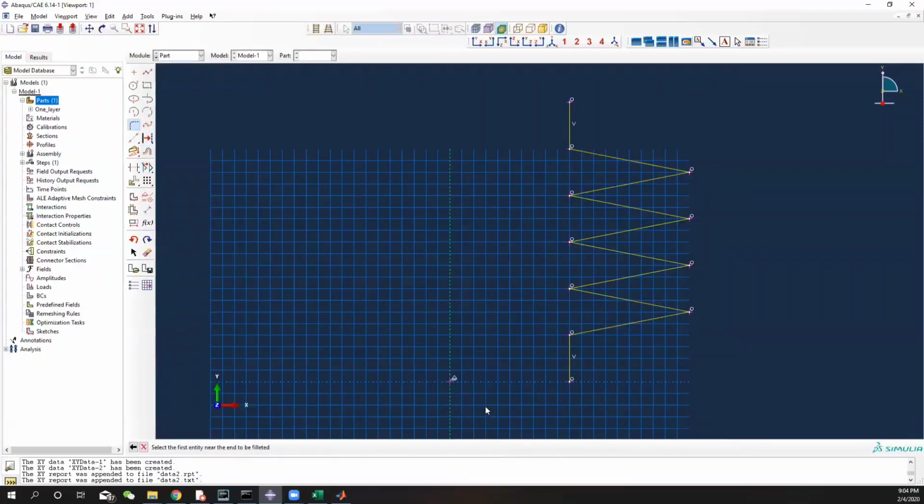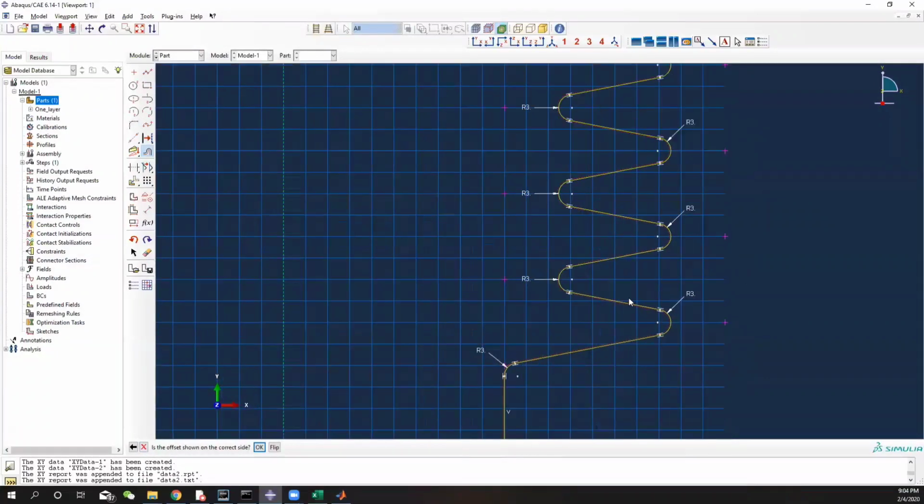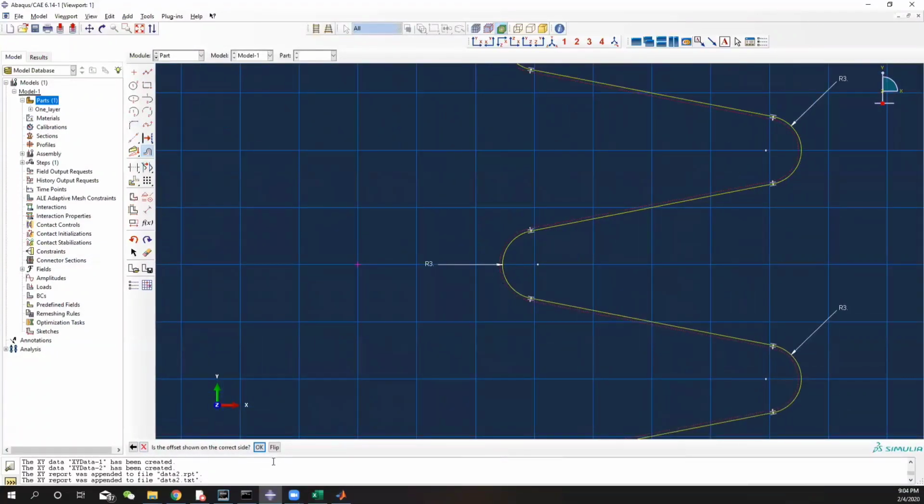Again, 3 millimeter, and then just create a Phillips. Okay, once it's done, let's make the offset. Selecting this curve down and 0.25. So click enter. You can see it's moved to the left a little bit.